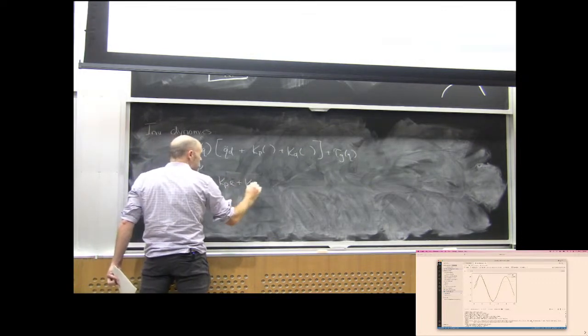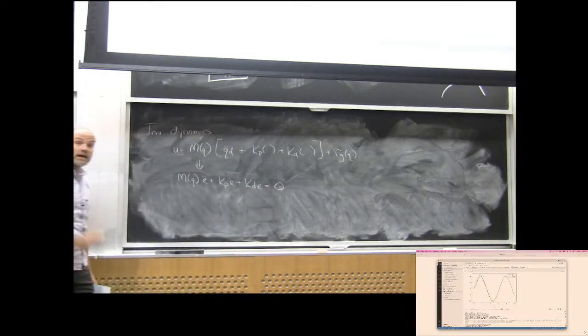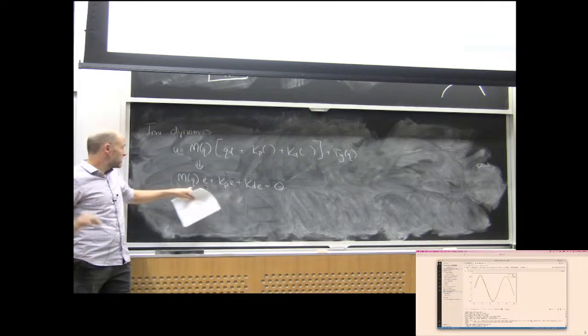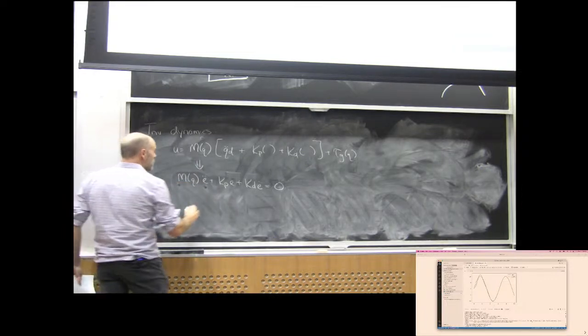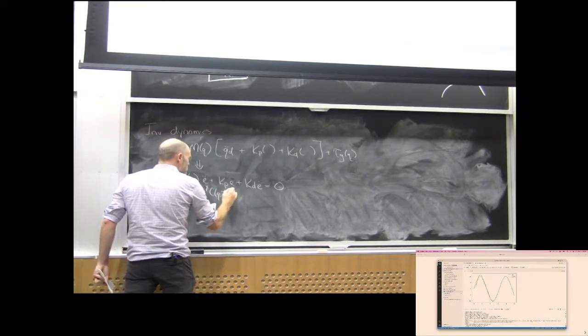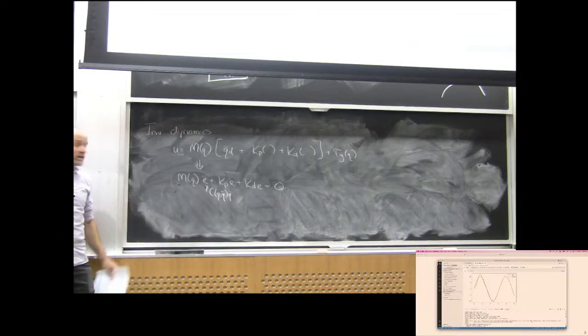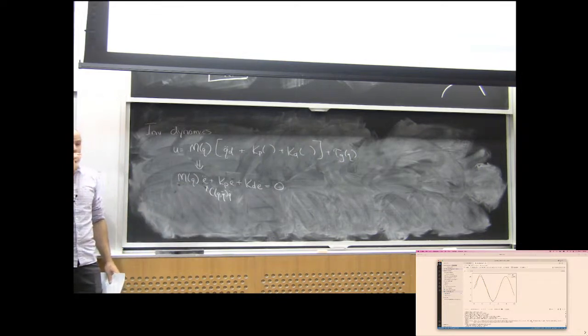I keep switching my e dots and whatever, but it looks like this. The error dynamics in joint space will converge like a second order spring with a more complicated mass matrix. It actually has the Coriolis terms too. Like I said, those two go together. Those are still there, okay? But it's a more complicated mass spring damper system, but the error converges to 0. So this is a nice way to do high-end trajectory tracking control.